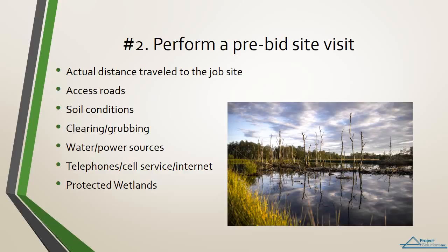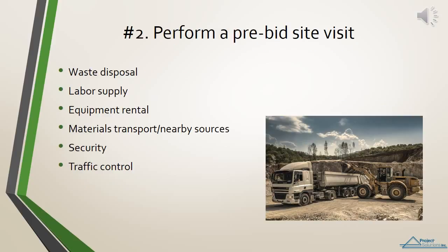Are there nearby sources of water and power? Are telephone lines available? What about cell service and internet? Are there nearby wetlands, streams, lakes, etc. that will need to be protected? How far is the job site to an adequate waste disposal area? If additional labor will need to be hired, is there an adequate supply of labor in the area?